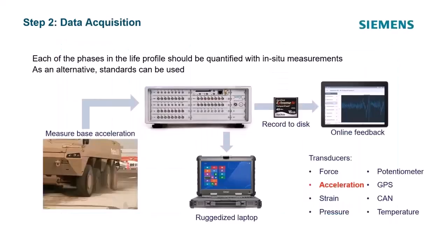The data we take, again, is pretty straightforward. It's the input into the structure. So if it's this rear view mirror, we want to get here. Now, if you were to have a bigger structure with maybe multiple attachment points to where it was mounted, you could then take multiple input accelerometers, and then we could envelope across there to get the worst case.